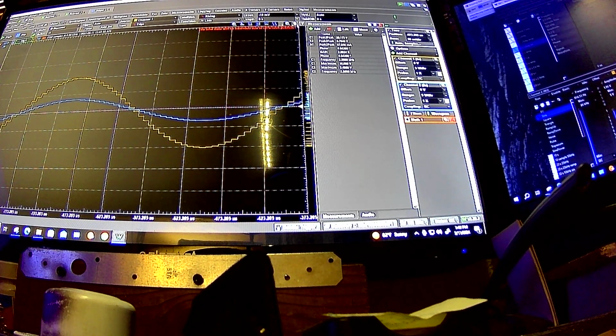So if you had like a 6-bit DAC, at some point, even if you're not using all your resolution peak to peak, you're going to still be running into having to change your waveform data, because you've got fewer vertical bits to work with since you're trying to make a lower voltage signal.